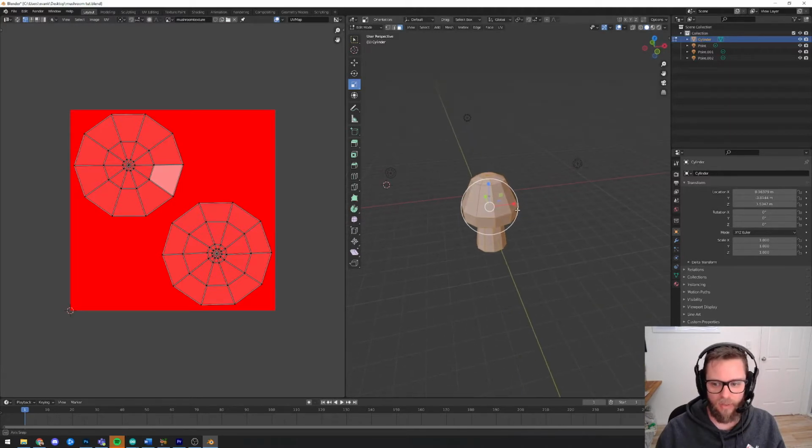Now there are a few things that we need to do to get this to display over here. The first thing that we want to do is click up here in your 3D view, right up where we were dealing with the transparent button last time. You've got these four spheres. The current one that should be selected just looks like a white circle. If you hover over that, at the bottom of the little pop-up it says display in solid mode. The next one across looks like the beach ball that we used last video, but it's not colored, and if you hover over that it says display in material preview mode. You want to click on that.